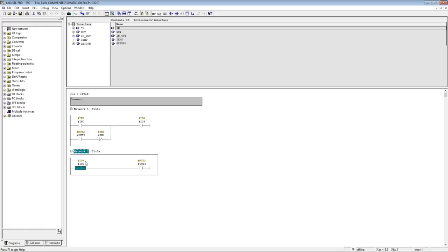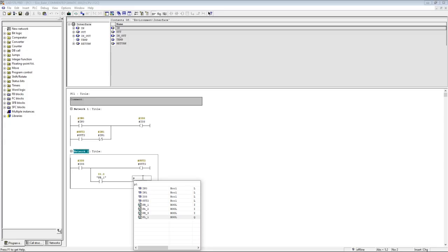Now, just to prove that that worked out, we go into edit mode. Let's give myself a little branch, and then we're going to come over here. And now, when we come over here, we got I0.0, hit enter, push button 1. Now I'm going to need a coil. Let's use our pilot light. PL1, PL1, booyah. And now it's labeled, and as you can see, it's Q0.0 and I0.0, and those are 2 inputs and outputs we just put into our symbol editor.